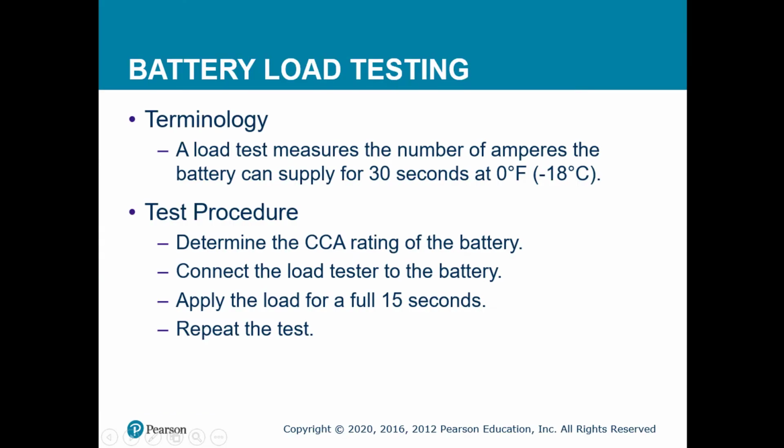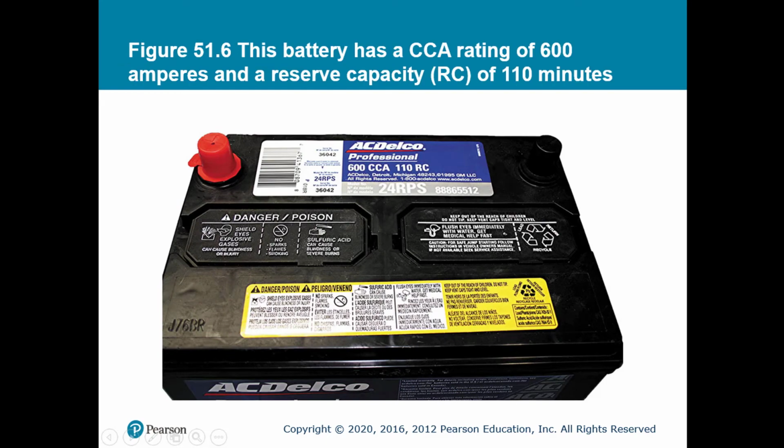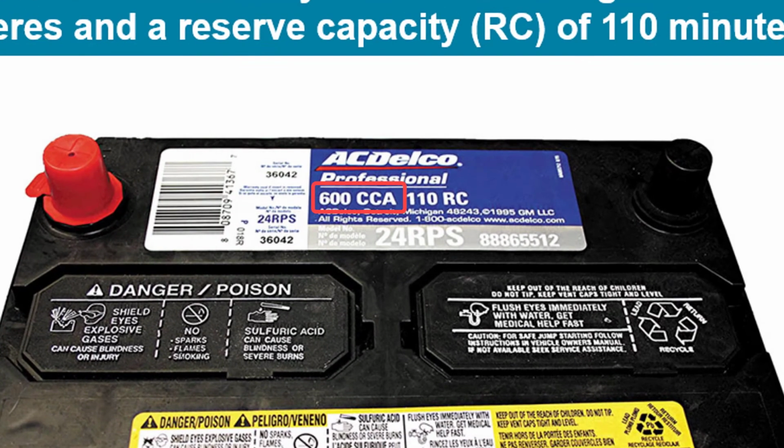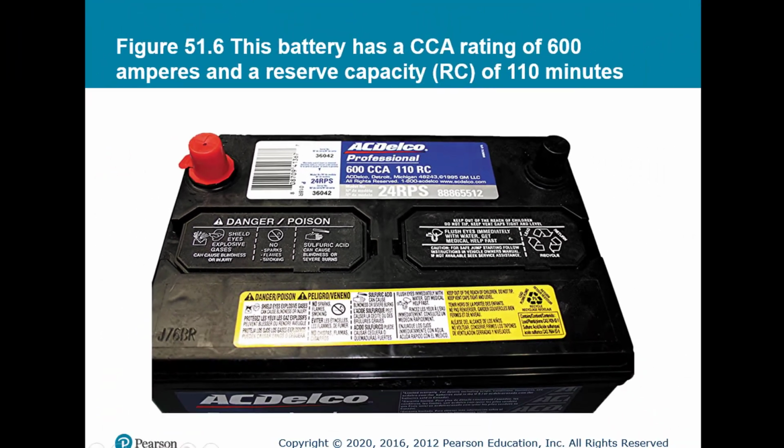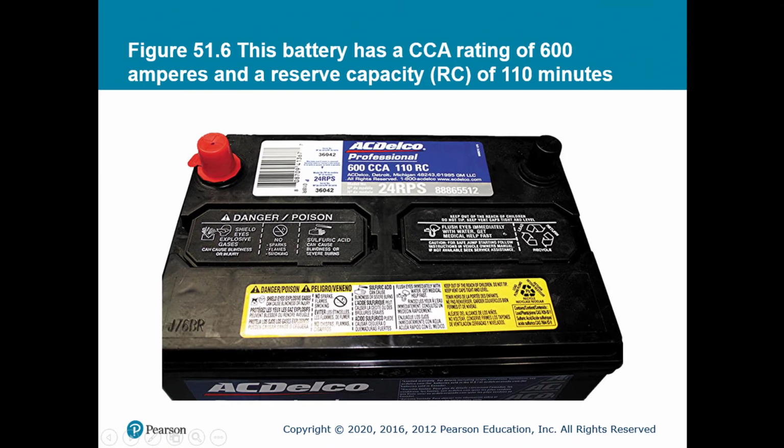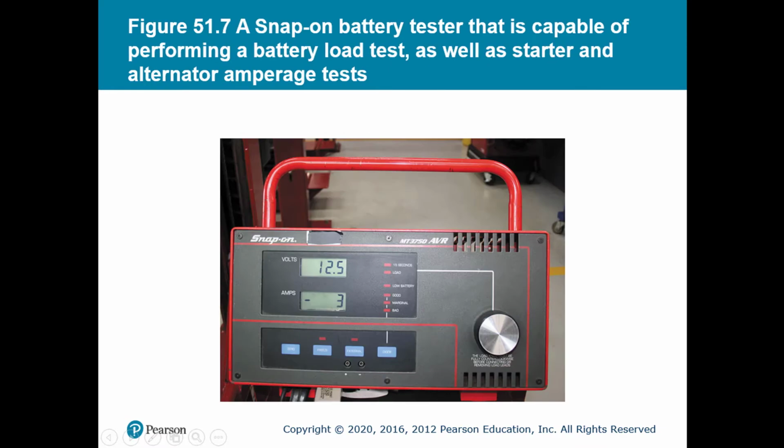As far as load testing goes, nothing beats a load test because you're actually putting a physical load on the battery and you're putting it under a strain. So load testing is great, but you want to make sure that the battery is fully charged before you do a load test. In this example, I want to make sure that my 600 CCAs is what this battery can put out. So I want to test it at 600 CCAs when I do my load test. And this is an example. This is a Snap-on tester that can actually put a physical load, a carbon pile load, on that battery to truly tell.